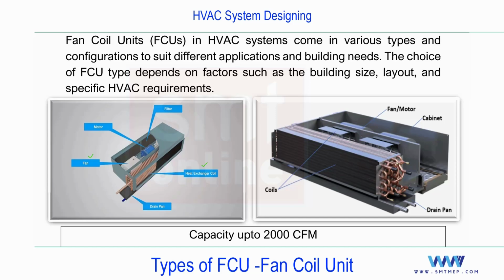Next, the fan. There's a fan casing, and inside you'll find the fan motor. It can be one casing with one fan motor, or two fan motors, depending on the capacity, configuration, and make. You'll find the fan motor and the filters. And you see here is a cooling coil with a bunch of fins. These are the two fan blowers, and in between you'll find a motor with two shafts.